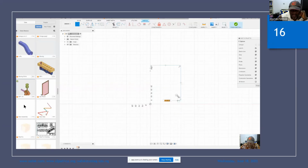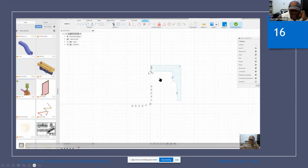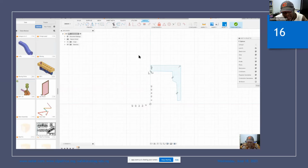It should be horizontal, but it doesn't have to be because we can use the constraining tools to do it. Then go up about 20, then a little bit left, and then up again, and then close it. You'll see that once you close it, it changes color. That bluish color shows you have a closed profile. It's only on a closed profile that you can create your three-dimensional bodies. If the profile is not closed, it won't work. So you are reminded when you have a closed profile.